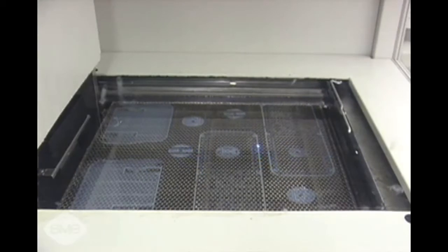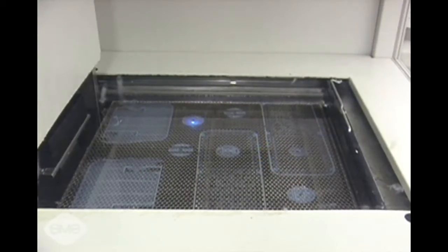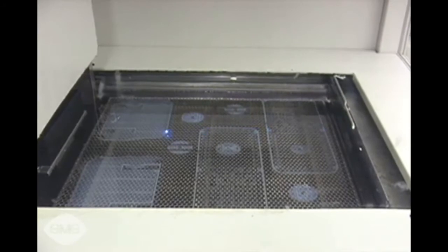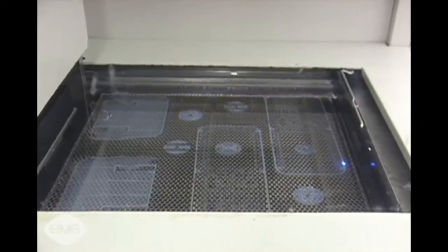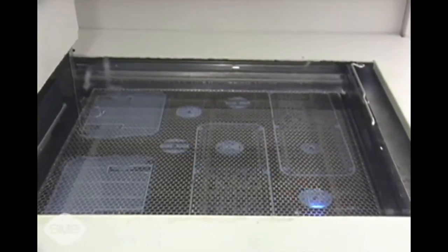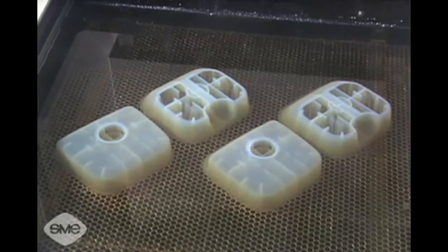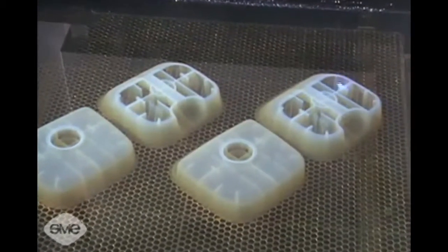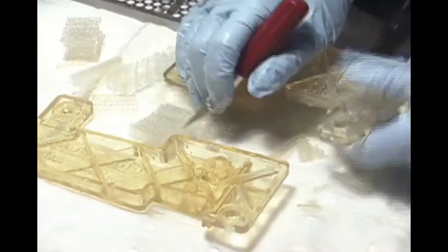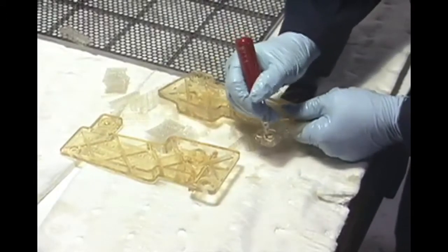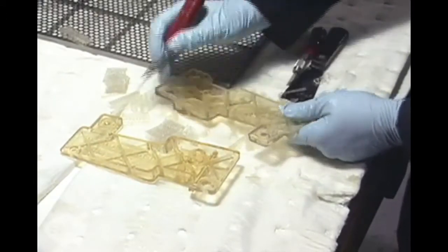Stereolithography machines can produce models as large as 40 by 32 by 23 inches. Additionally, multiple smaller models or model components can be nested together for simultaneous building. Models made by stereolithography can be extremely precise, with thin and sharp features and smooth finishes. Substantial post-processing may be required, however, to separate the model from its supports. Additionally, polymer cost is high.